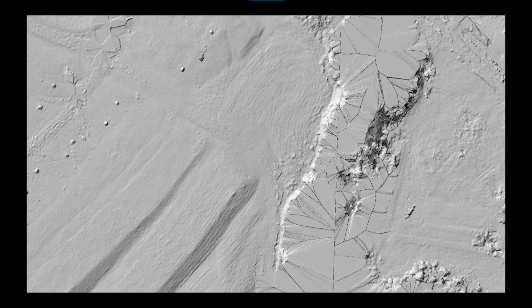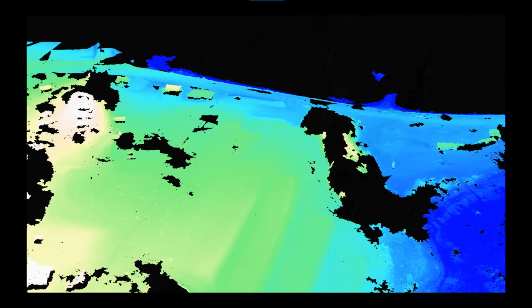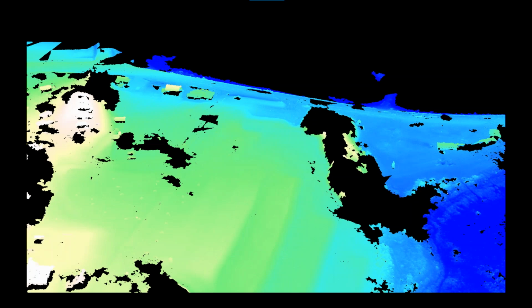And so one of the things you probably want to consider when you're specifying your deliverables is to get what you see here. This is the point cloud for that project. We're looking at it from a slightly different perspective, but you can see that mound over on the right there again. There's no points. No points indicates no matching between images, which means we've compromised the accuracy of our data within that specific area. Okay, small gaps are always going to occur, but if we're really interested in making detailed measurements in that area, we need to keep in mind that the data might be slightly compromised.